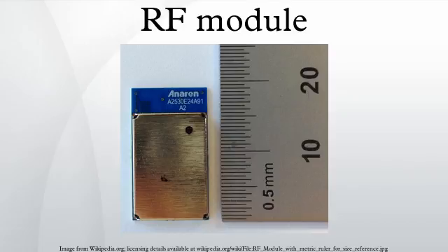Module physical connection. A variety of methods are used to attach an RF module to a printed circuit board, either with through-hole technology or surface mount technology. Through-hole technology allows the module to be inserted or removed without soldering. Surface mount technology allows the module to be attached to the PCB without an additional assembly step. Surface mount connections used in RF modules include land grid array and castellated holes. The LGA package allows for small module sizes, as the pads are all beneath the module, but connections must be X-rayed to verify connectivity. Castellated holes enable optical inspection of the connection but will make the module footprint physically larger